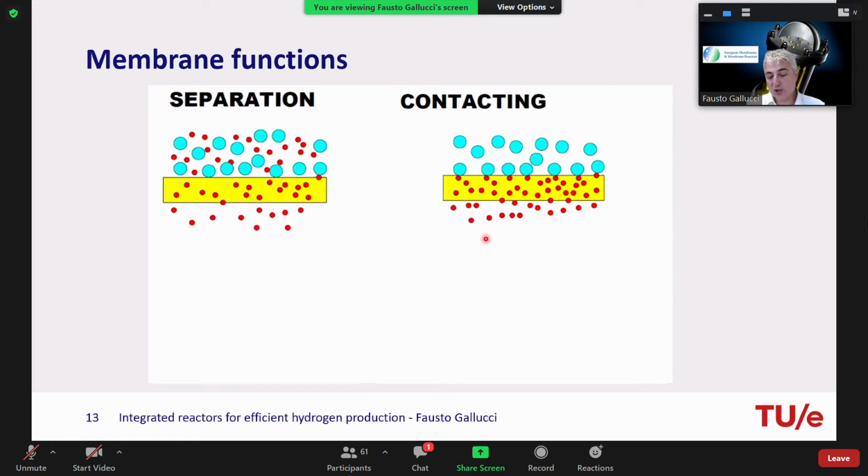Normally, the absorption is done in packed column or tray columns. Why do we use membranes? Simply because the contact area, when you use a membrane contactor, can be 1,000 times or 10,000 times bigger than when you have a very simple vessel. And of course, the contact area is one of the components for the transfer of material between the two phases. That's why you can use a membrane contactor.